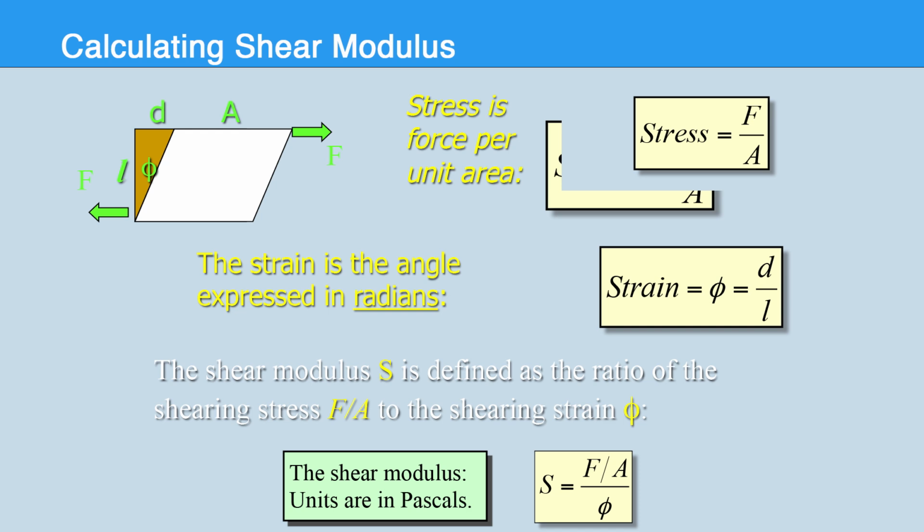Shear modulus is shear stress tau divided by shear strain gamma. That is its mathematical formulation, where shear stress is the force per unit area acting parallel to the surface of the material. Shear strain is the angular deformation, or change in shape, in response to the shear stress. The SI unit for the shear modulus is the Pascal, which is equivalent to the Newton per meter square.